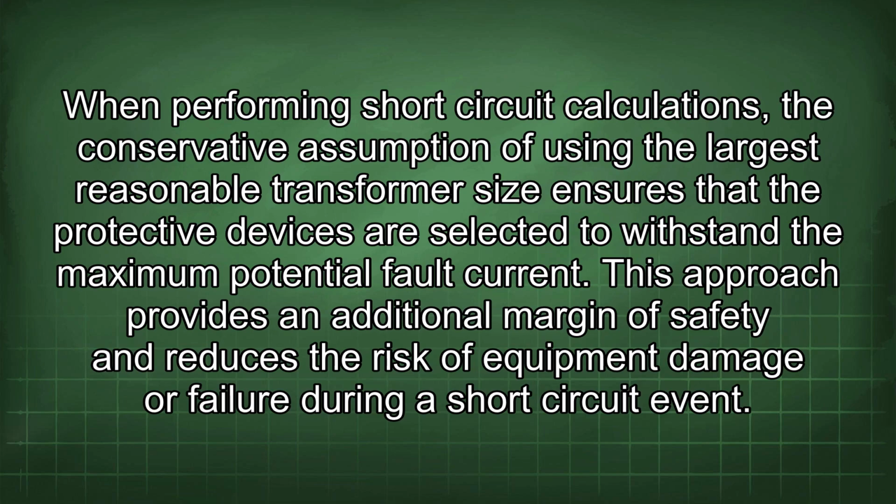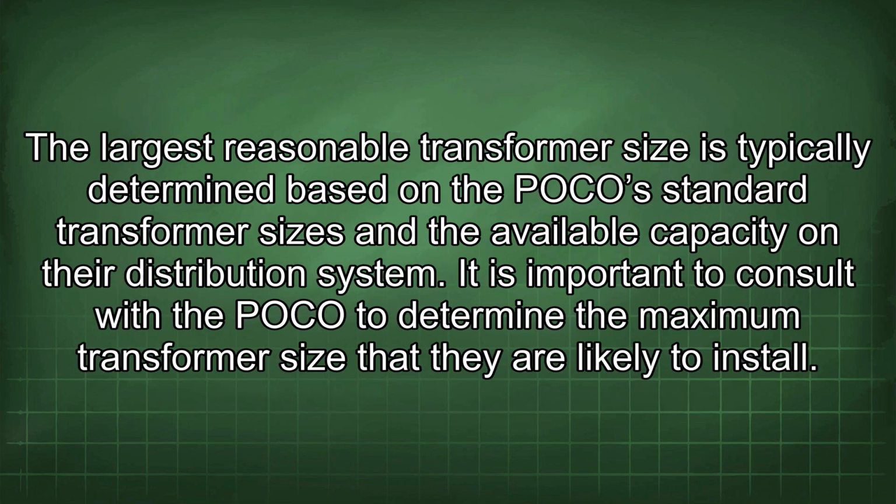When performing short-circuit calculations, the conservative assumption of using the largest reasonable transformer size ensures that the protective devices are selected to withstand the maximum potential fault current. This approach provides an additional margin of safety and reduces the risk of equipment damage or failure during a short-circuit event.